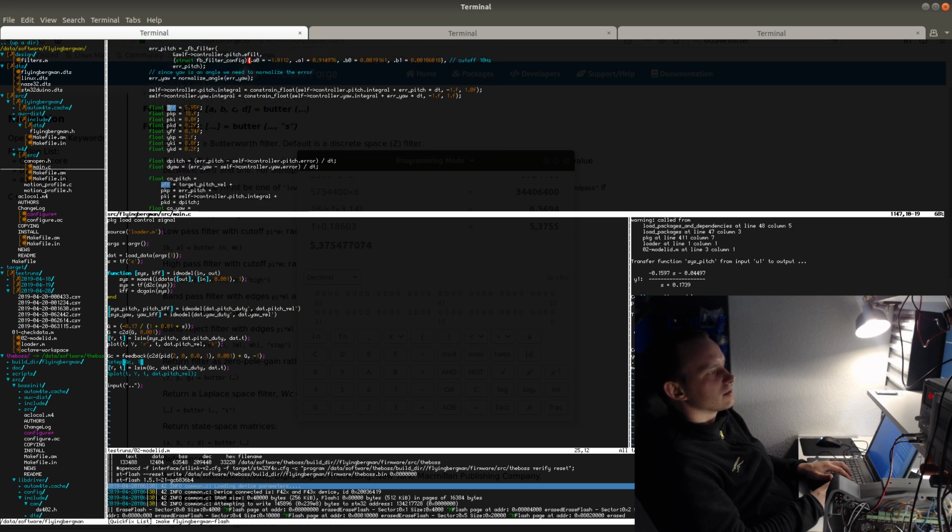And the feed-forward value here ends up being the DC gain value, which I got from the model identification. But 1 divided by that value. So in this case, 1 divided by 0.17.